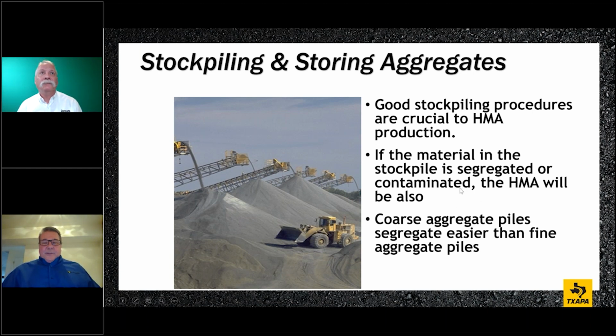Yes, sir. Absolutely. And coarse aggregate piles segregate easier than fine aggregate. Anybody know why? Coarse aggregate piles will segregate easier than fine aggregate. If you've been in a sand pit or anywhere else, that coarse aggregate will roll to the outside. As they're making the stockpiles and building them and loading them, that coarse rock will run to the outside. So it's real important to pay attention to your stockpiling and storing of aggregate.